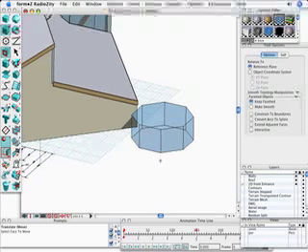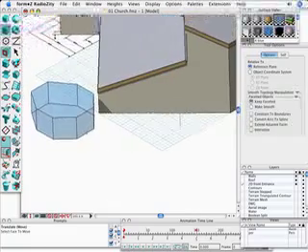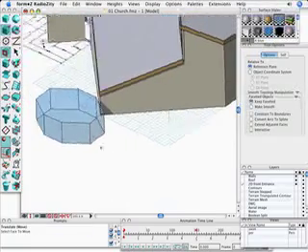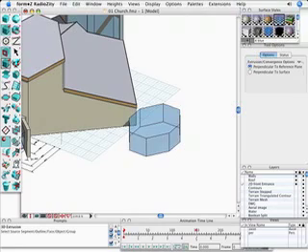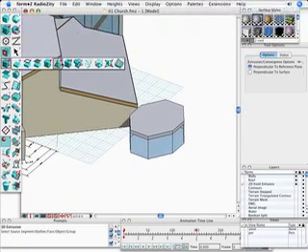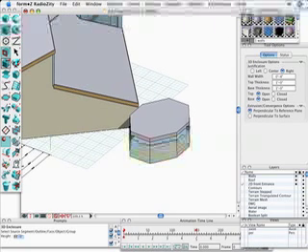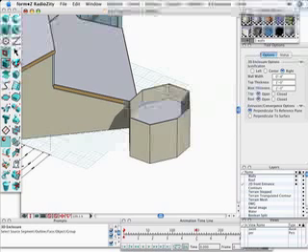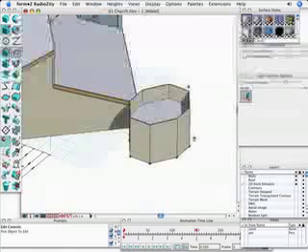Let's change the shape of that by grabbing a face and pulling that out just a little bit and sculpting that area into the volume that we want. And then to add a roof, once again, we'll go back to our derivative tools, extrude a solid slab, and the 3D enclosure tool will then allow us to just simply click on that outside boundary edge and create a wall around the outside.